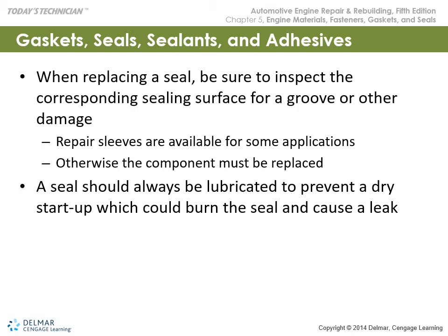There are some specialty shops that can heat the crankshaft up to about half of the final heat treating temperature and spray on molten metal, cool that in a very controlled cooling application, and then grind it down to the original outside diameter that it came with. That is available in specialty shops, and it's only cost effective if you're utilizing it on a high-valued assembly.